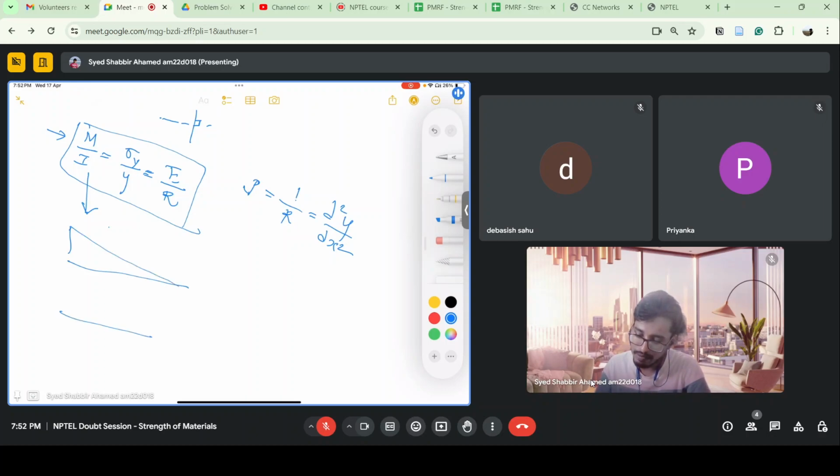Like if I have a cantilever beam with applied load like this, my bending moment diagram will look like this. If I go to some point, I can use this formula to get the bending stress. I can again go to another point and use this formula to get the bending stress. Obviously, there will be shear which will also give stresses, so I have to use the shear formulations whatever we have learned for shear. We have to get the shear stresses and we can sum them up.